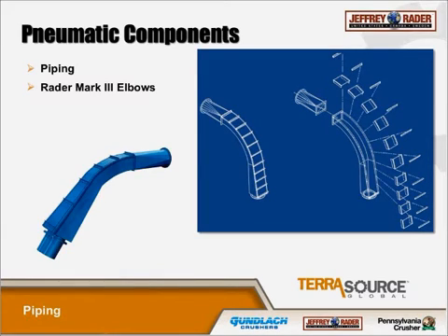As you can see in this image, the high impact areas are easily removable and replaceable. We also offer proprietary blends called R35 cast segments, which are extremely wear resistant. It's not an exact thing, but it will typically see 6 to 8 times the wear life of AR200. Kind of gives you a frame of reference. You don't want to be changing these things out very often. It's just more downtime, loses more money.